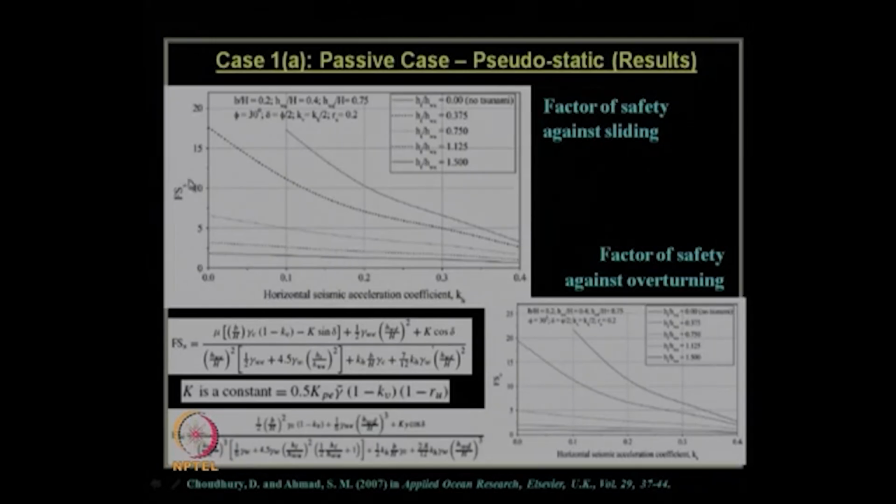This will give us the factor of safety of the wall against sliding for a chosen other input value as shown over here. So, if it is not satisfying the stability criteria of 1.15 minimum factor of safety against sliding under earthquake condition, then we have to redesign this wall section to withstand both seismic acceleration as well as the tsunami wave height at a particular region.